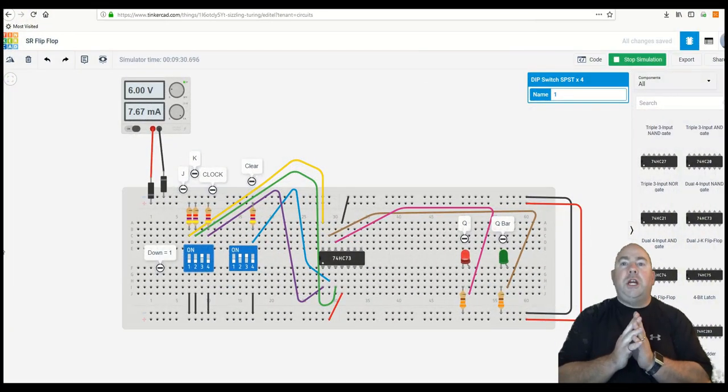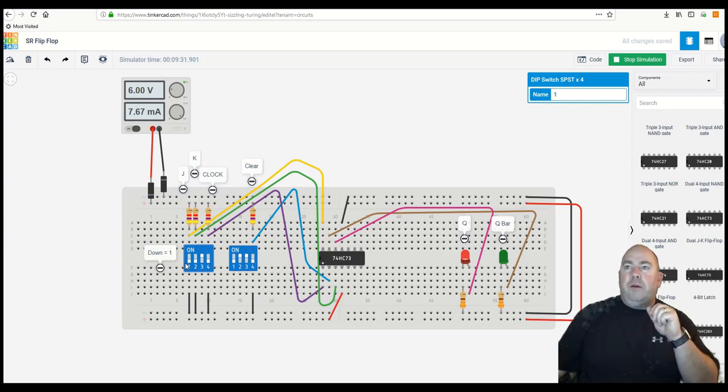Okay, this one is the JK flip-flop. This is our final flip-flop we're going to be dealing with. This one is interesting because it does a couple new functions. For one in particular, the toggle function that the other ones don't do. So for this one, according to the book, now we can't do the one that's in the book or in the lab. We don't have that chip. I think it's a 112 chip that it shows being used. We have a 73 chip, which is a JK flip-flop, but does not have a preset function to it.